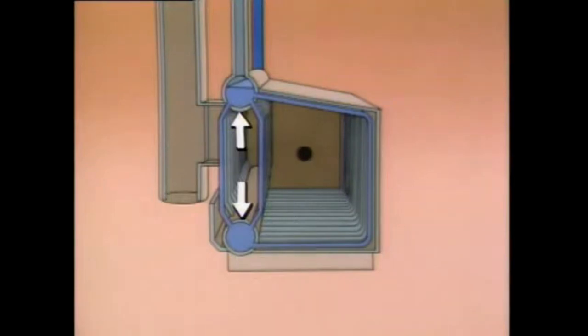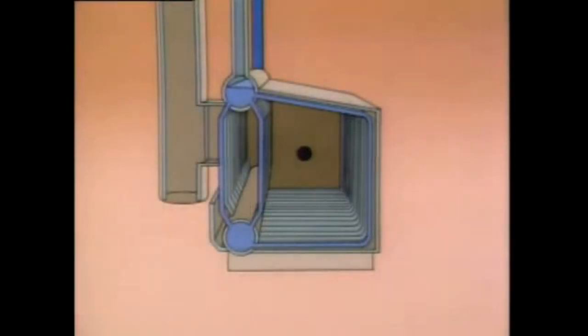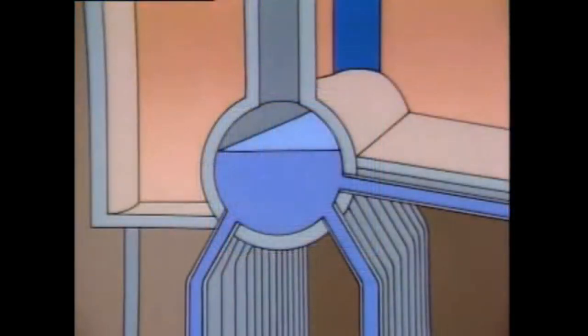The drums distribute water to the tubes. The water tubes connect the drums and form a wall around the combustion area of the boiler. This is where heat is generated. Water is fed into the upper drum through a feed water inlet line. The water tubes and the lower drum are completely filled with water. The upper drum is only filled to a certain level. This provides space for steam to collect, so the upper drum is often called the steam drum.